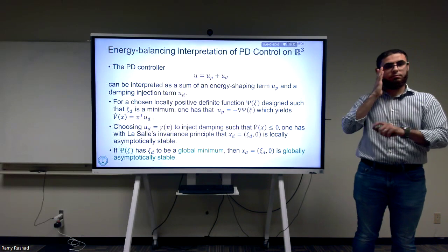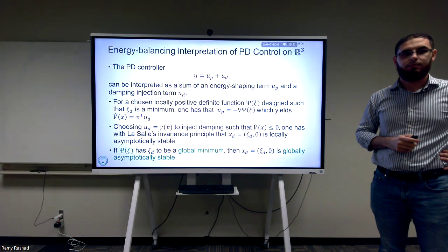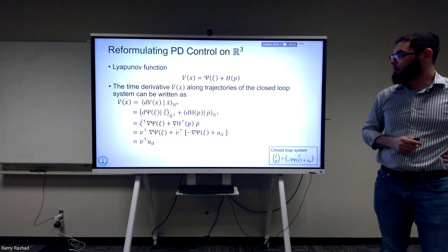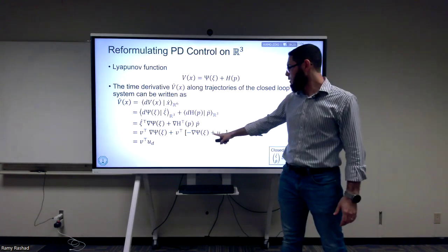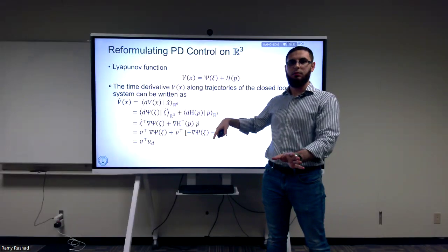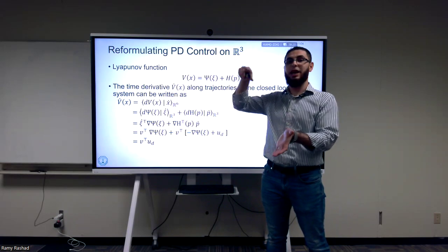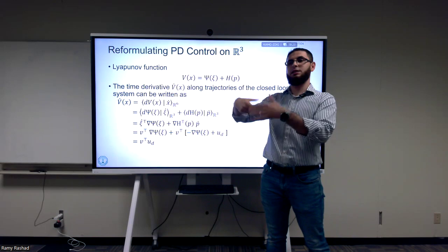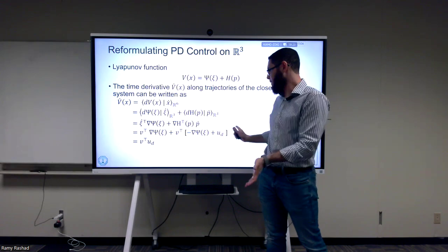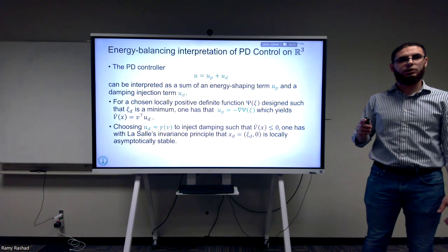Questions? Yeah. We chose p way back as a state only for ease of calculation, only to simplify. And it comes in here. You see? First of all, there was no m. If you do it with the v, you're going to have m all over the place. If you generalize this, for example with the satellite case, you're going to have, instead of the m, the J. And if you generalize this to the full rigid body, you're going to have the generalized inertia matrix all over the place. When we work with the momentum, everything is nice. Any more questions?